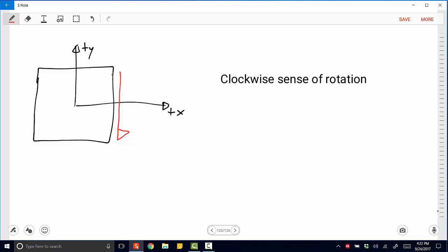Now, if we want to maintain equilibrium, then we need something to balance out the forces in the y direction. So we need to put a shear stress on this other surface. And then also, in terms of moment, if z is coming out of the page, these two shear stresses create a kind of couple moment. So if we want to counteract that, we're going to need another couple moment with equal and opposite values in order to balance this system.